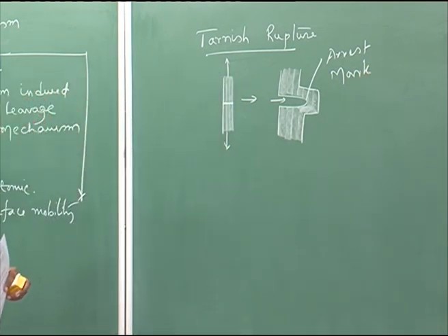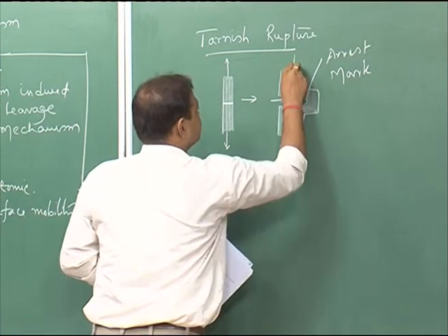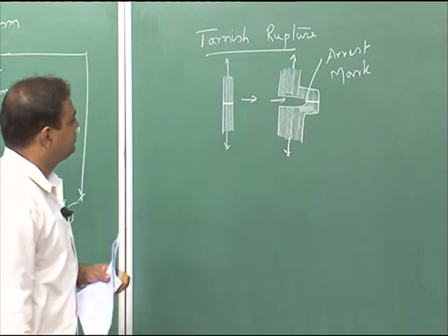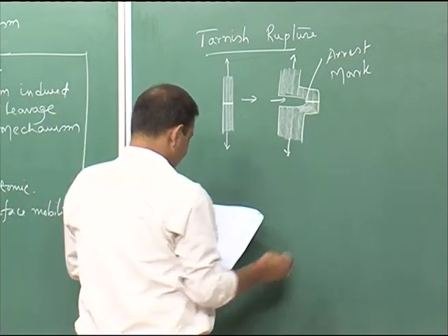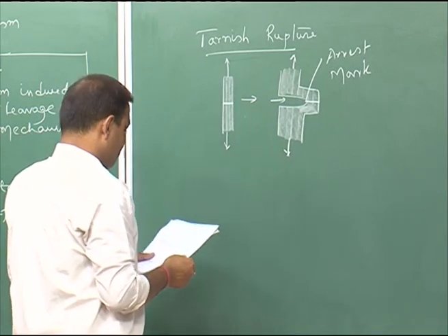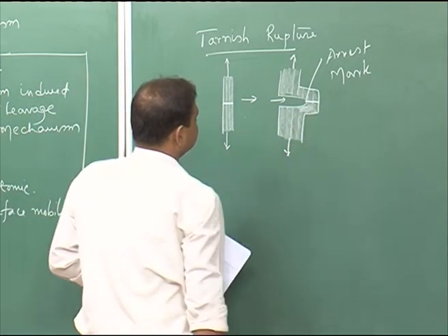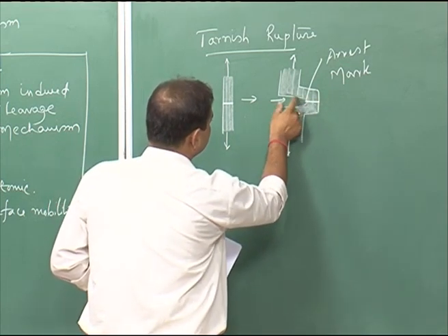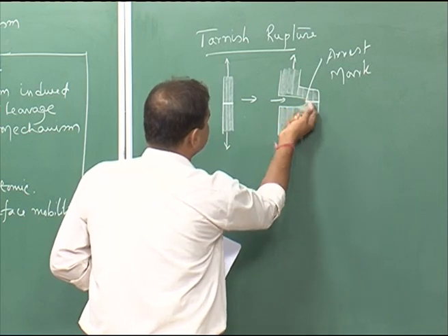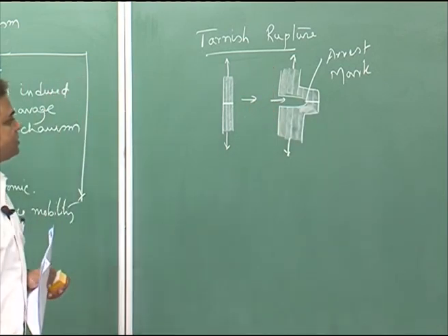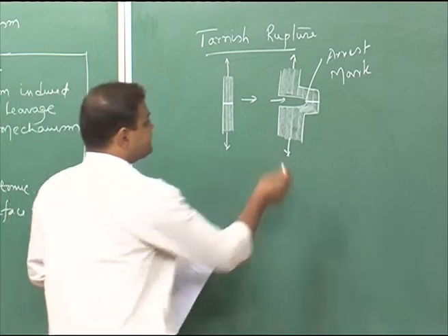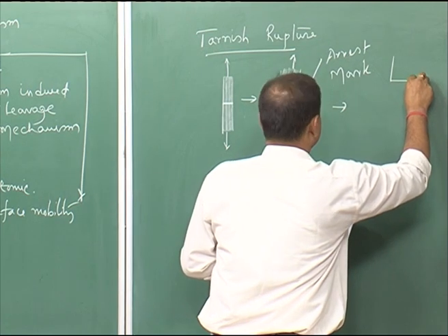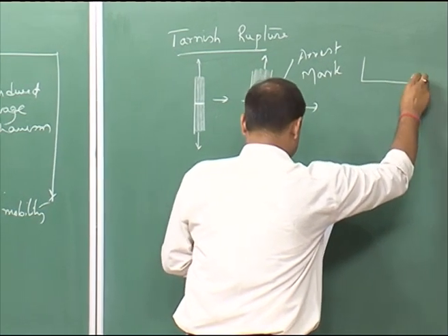Now, the second step, again this is under stress. So, again you can have a small crack formation here, and then the crack is experiencing the tough matrix. So, it is getting stopped here, and you also have the crack blunting, and this metal surface is exposed to the solution, and again the passive film forms. The next step would be again growth of this passive film, further growing of this passive film.